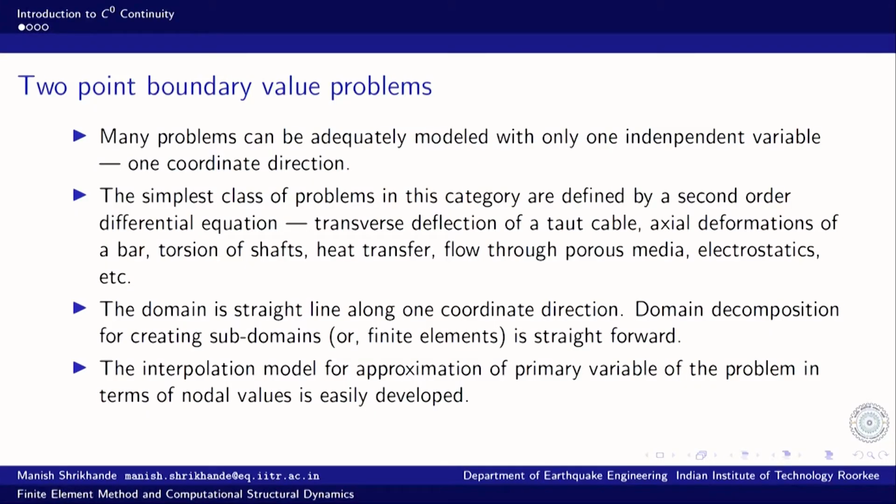And the interpolation model that we discussed earlier, the primary variable of the problem needs to be approximated, and we adopt an interpolation model. The interpolation model for the primary variable can be easily developed for one dimension, knowing the geometry. How that is done we will see in a short while.